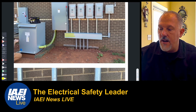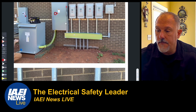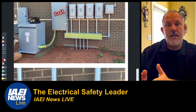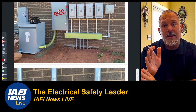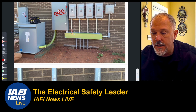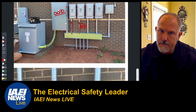The conductors in this trough in yellow here, this is a feeder because it's protected at its source right here. There's an OCPD, an overcurrent protective device, a fuse in that fusible disconnect switch. So the conductors that originate at that fuse and beyond, that is a feeder. And then we go to a smaller conductor up to these switches. And I believe those are number 2s, 2 American wire gauge, if I'm not mistaken.